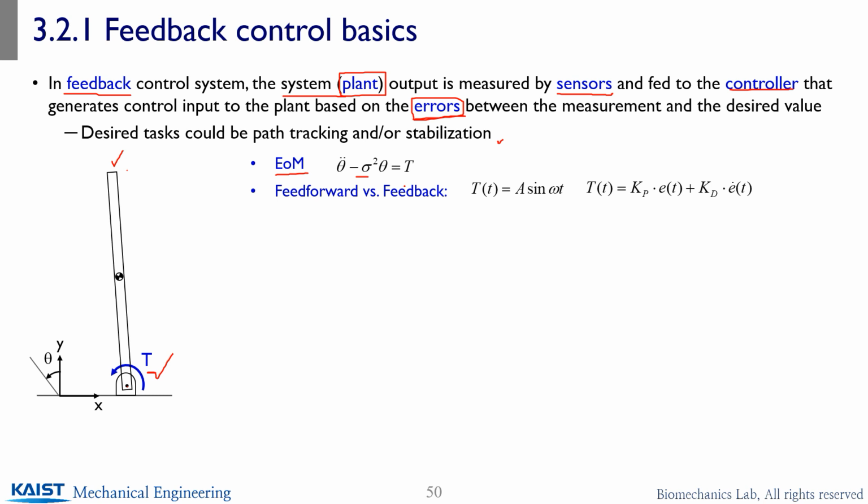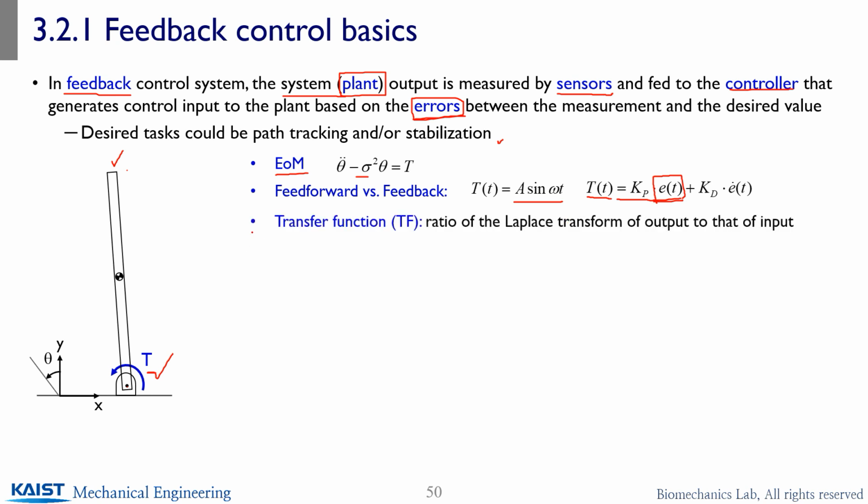Versus feedforward versus feedback: in feedback you actually measure your output and send it back to calculate the error. So your control input is a function of the error, the measured output, the feedback information. However, the feedforward information here doesn't use the error value or your measured output value. So feedforward is just one directional, while feedback actually gets the signals coming back. That's the difference.